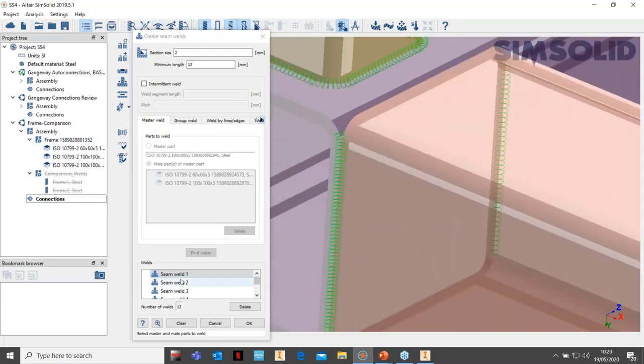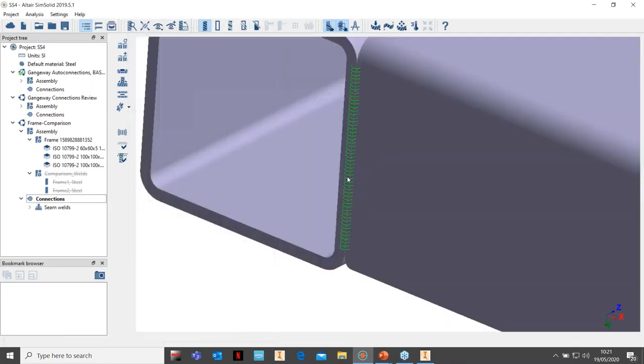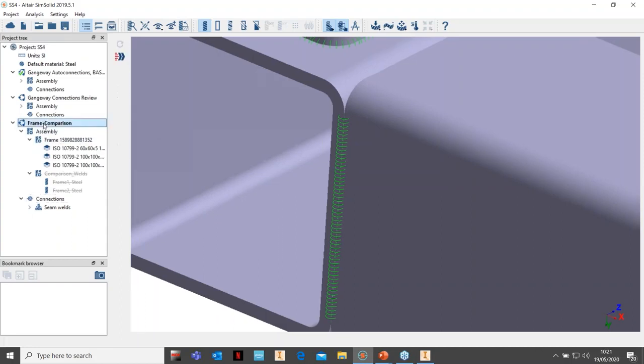And so let's have a quick look here. What's this done? If I just go through these options here, that's a weld between the radius, so I can delete that one if I wanted to, and then the same, keep going through the welds. And the next one, and that one there again. So you can basically create welds like that. So if I just press OK. Basically what it's doing here is connecting the edges to the faces, or the edge, depending on what the connection here is. Now what we can also do here, let's pick another example.